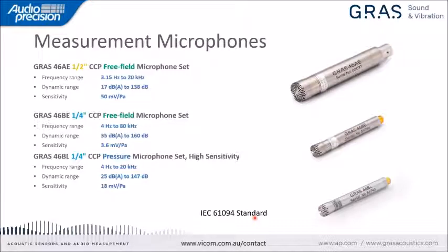These microphones, or measurement microphones in general, are optimized to have a flat frequency response in a particular sound field. They typically have a dynamic range of around 120 dB, and something that is very important is that these sensors can be calibrated according to references that are globally traceable. So measurement microphones are reliable measurement tools that have long-term stability for the frequency response and also for the sensitivity. And if we check most standards that refer to acoustic measurements, these standards will typically refer to measurement microphones for capturing acoustic signals.